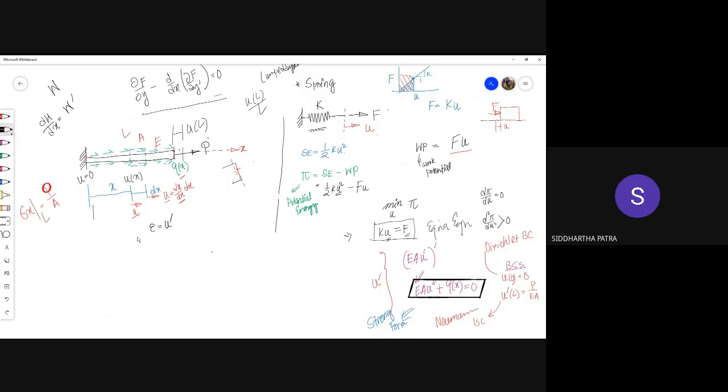then what should be the expression for strain energy? Can anyone tell me? Half epsilon square by E. Epsilon squared by E. So half into sigma into epsilon, half into sigma into epsilon into volume. Okay. So it's basically compared with the spring diagram, stress, strain, Hooke's law, slope, Young's modulus. You are at certain strain. So this is what is strain energy.